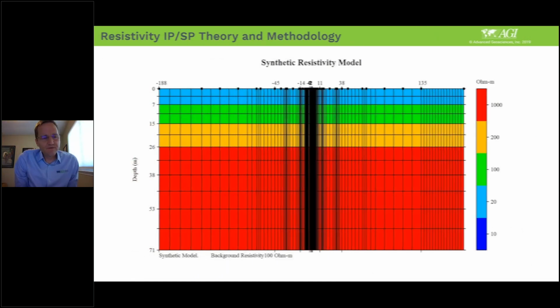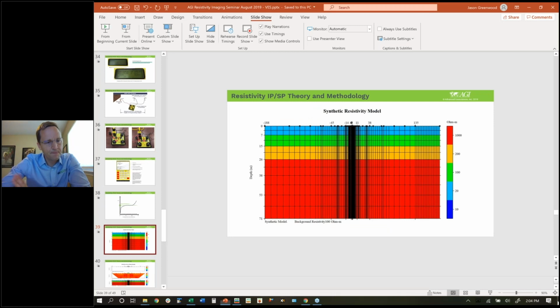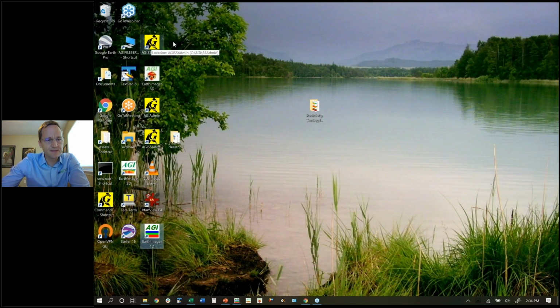Okay, so we've talked about these 1D soundings, and there's been some questions from some end users that are very active in these types of tests. How do we account for a clay lens over the top of rock? Now the actual resistivities themselves, if you look at this model, this is a Wenner sounding. This is the measurements you take with a Wenner sounding. I'm going to show you what that looks like sped up if it were to be automated, if you had an automated type system.